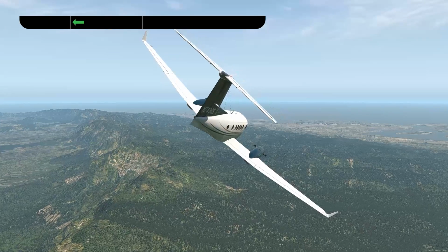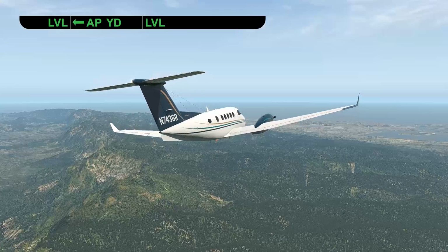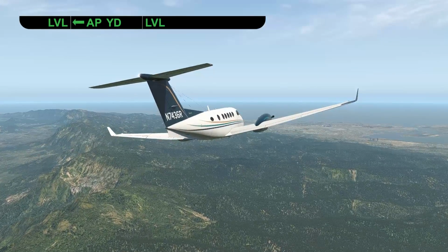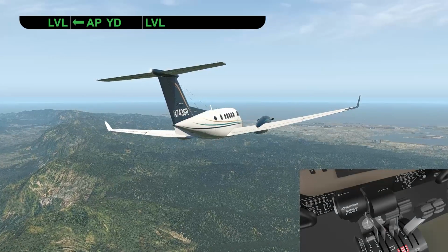While electronic stability and protection, or ESP, is primarily a function of the autopilot, the autothrottle can assist with ESP recovery and emergency descent mode. If the autothrottle is active when ESP activates the autopilot in level mode, the autothrottle will continue to track the speed target prior to level mode activating. The autothrottle will not automatically engage with the activation of level mode.